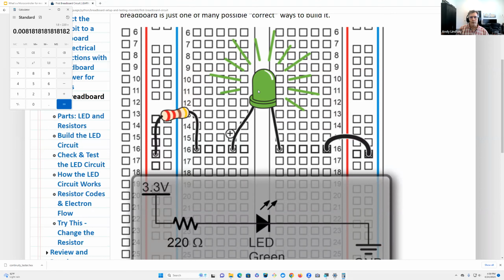Oh, that's the problem. I got my voltages reversed. It's 2 volts across the light. So basically it's going to be 0.8. Yeah. So about 3.6 milliamps. That's more reasonable as where it tops out current-wise. For anybody who is new to this, that question and answer is addressed I think on Wednesday, so we'll be talking about electrical properties like current and resistance.